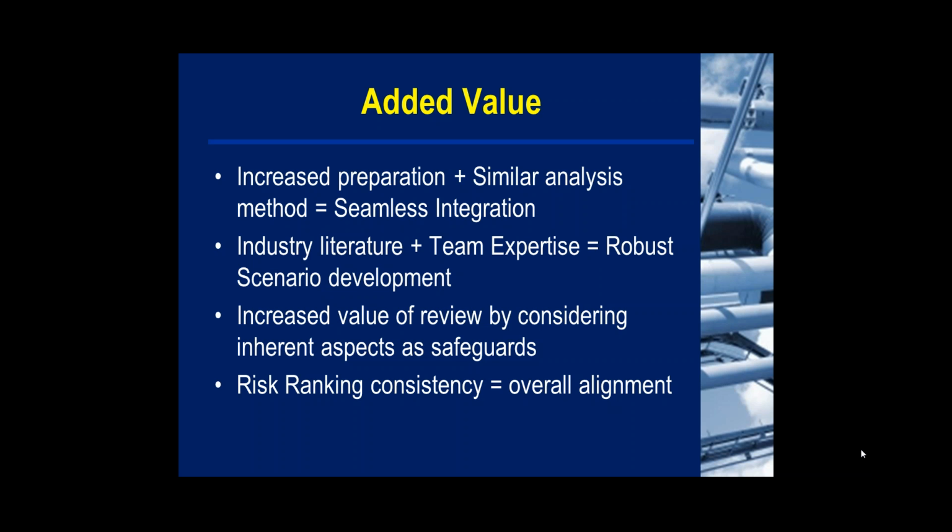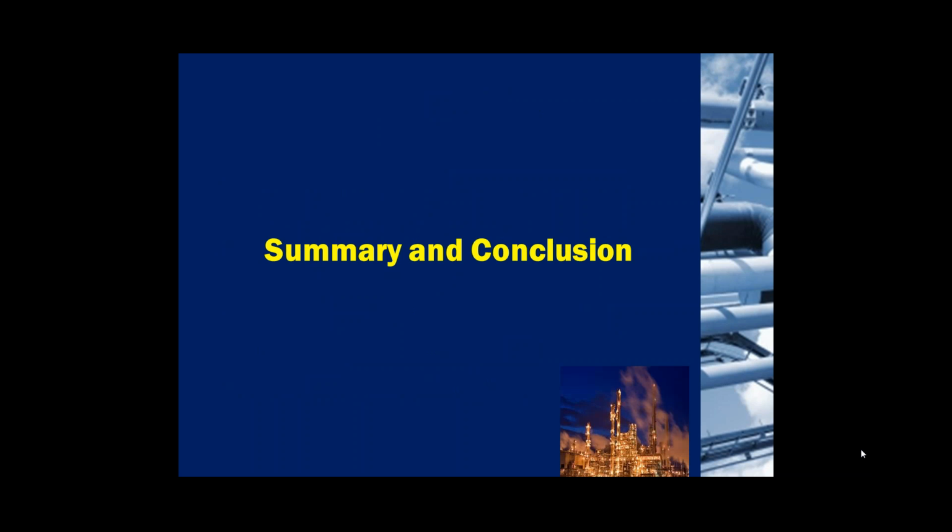You'll see that the risk ranking matrix looks very similar to a standard HAZOP one, as we described earlier. And the comments is used to reference the reference material that was used to develop the full scenario here. For documentation, as you saw, the worksheets, we want to maintain a relative consistency, and that consistency will provide synergy among the report, the worksheets, and again, for IPHA action items. The IPHA, as HAZOP was, is primarily a reference tool, and having a common worksheet and common documentation style will only create ease of reference later on.